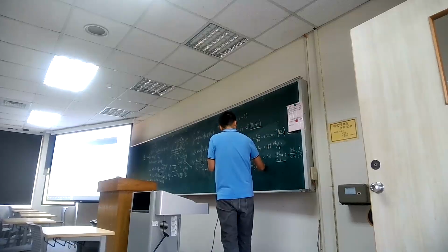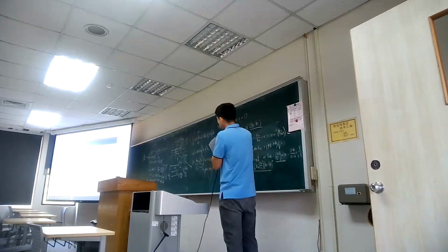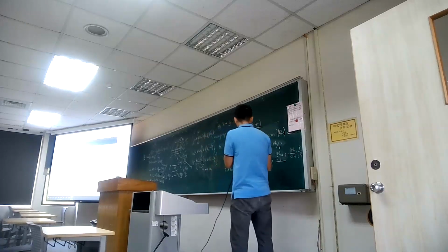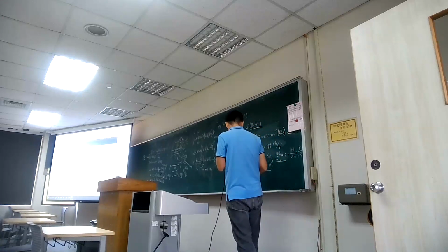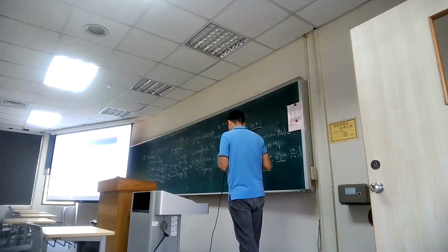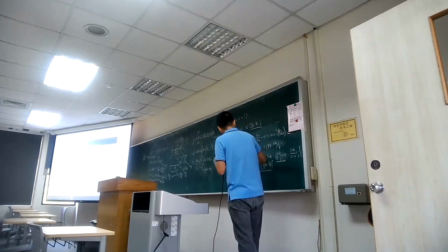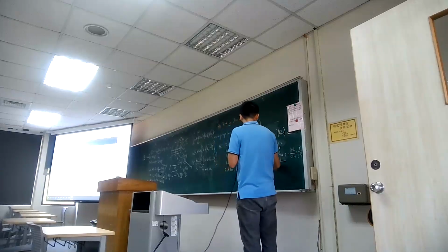So that will be 1/2 K_n' W over L (VGS minus VT) squared. Okay, so it is the equation in the saturation region. And if you want to say it is 100 micro, it should be 100 micro A, right?